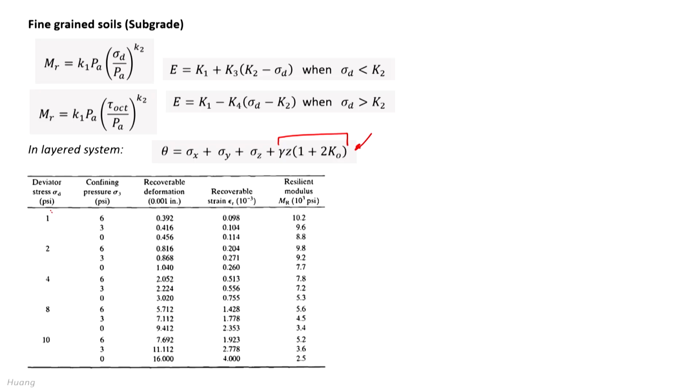Well, for testing cohesive soil or fine grained soil, in the first case, that is granular soil, which we discussed in the last slide, we saw that the value of sigma 3 is held constant and sigma d changes. But here we consider sigma d as constant, and at each sigma d we change the value of sigma 3, alright. This value of sigma 3 is gradually decreased from one particular value to 0, and then the response of the material is seen. Okay.